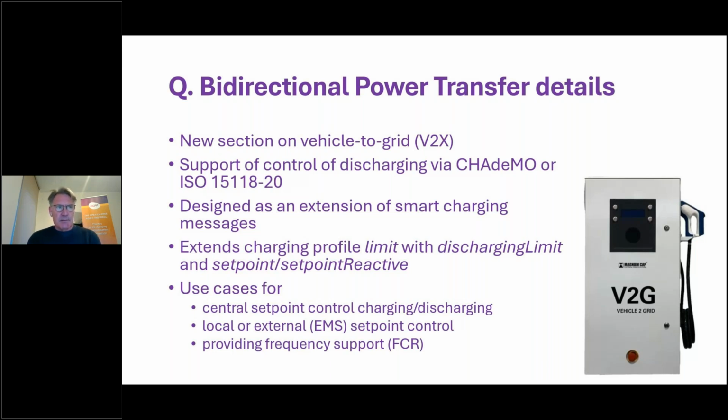And we have a new field called the operation mode that specifies whether you're now working in central set point control, or you're working with external set point control, or whether you're doing local load balancing, or whether you're not really there to charge the car, but you are there to provide frequency support. That's a whole different use case where you can configure a frequency watt table, and then if the frequency deviates from its nominal value, then you can let the vehicle automatically start charging or discharging.